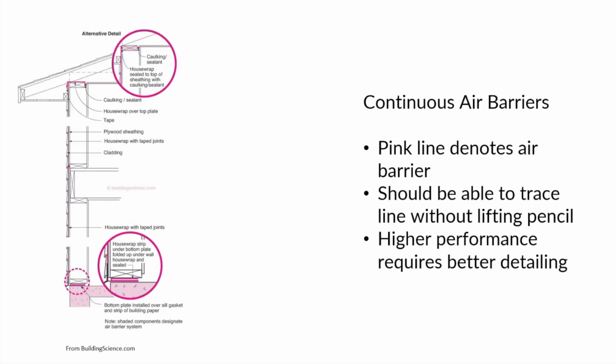The other thing is that cavity path. And so in that cavity path, we really want to think, for acoustics, about a continuous mass barrier, right? And typically that's our drywall. But in a floor-ceiling assembly, it may be your plywood subfloor and maybe gypsum concrete on the top, or it could be a CMU block wall or these kinds of things. But you want a continuous mass layer.